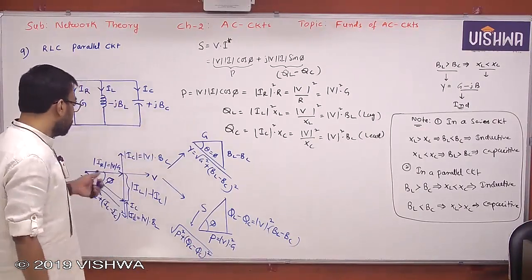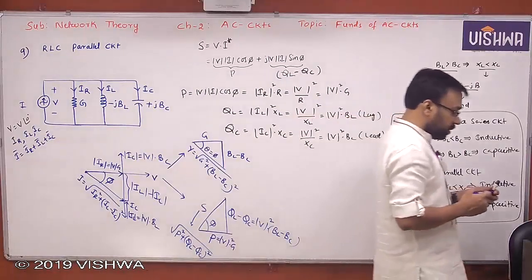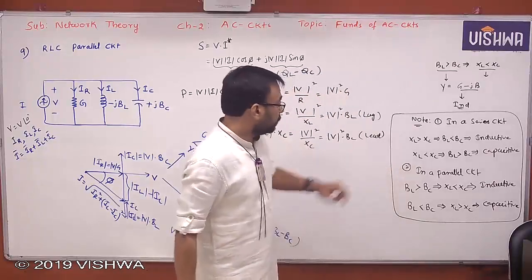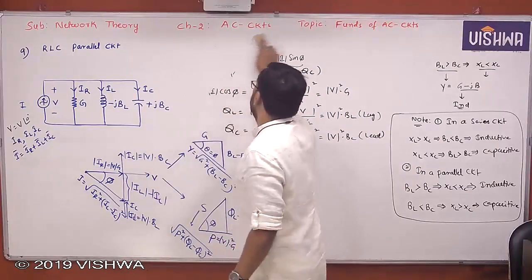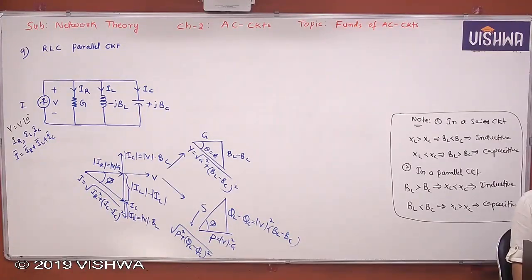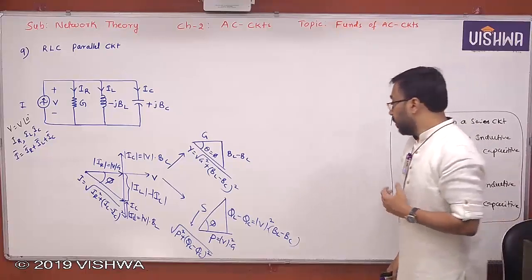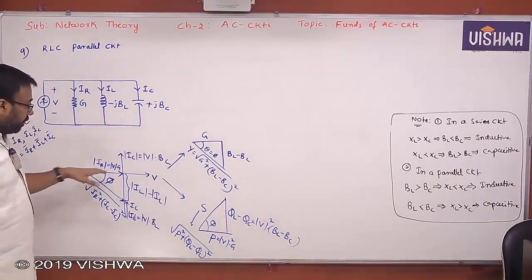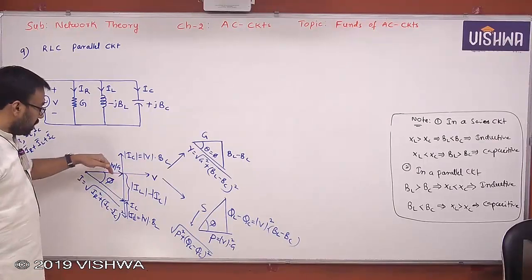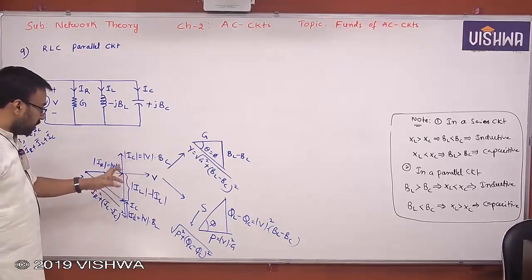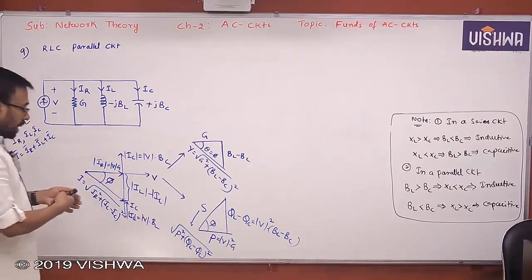Clear? So this is the phasor diagram for the RLC parallel circuit. All of you note down. And you also note down this part. Okay? Note down that part. Let me remove this meanwhile. Finish, okay? I hope you have finished this part. Phasor diagram. All of you understand? We have taken V as a reference phasor, then IR, then IL, because current lags behind the voltage, and IC, current leads the voltage by 90, current through a capacitor, right? So like that. So now let's take case 2.